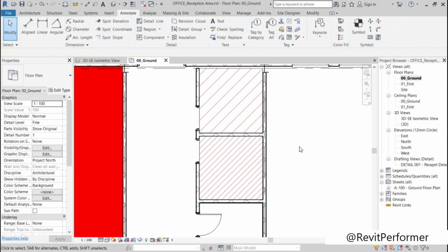Now, obviously, there are other ways of highlighting rooms and spaces. There's color legends available to you in Revit as well that allow you to actually utilize rooms and spaces and generate room legends. But it may be that you've got a linked CAD drawing come through. And what you want is you want your filled regions here in your Revit floor plan to replicate what you've got in AutoCAD. Now, obviously, the AutoCAD stuff does come through as imported categories, but it just comes through as basically a line projection setting. What you want is something in Revit that you can edit and update accordingly.